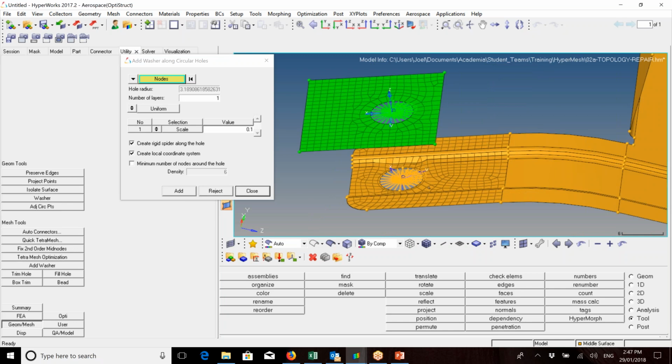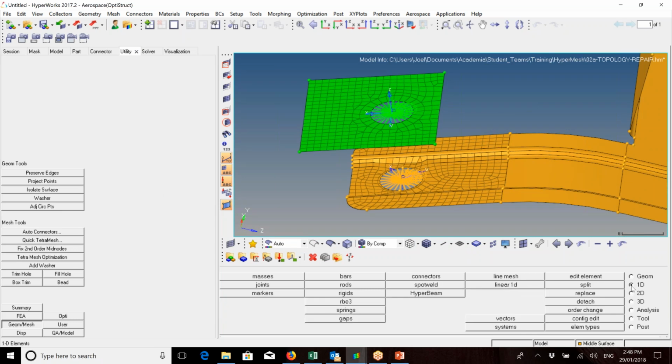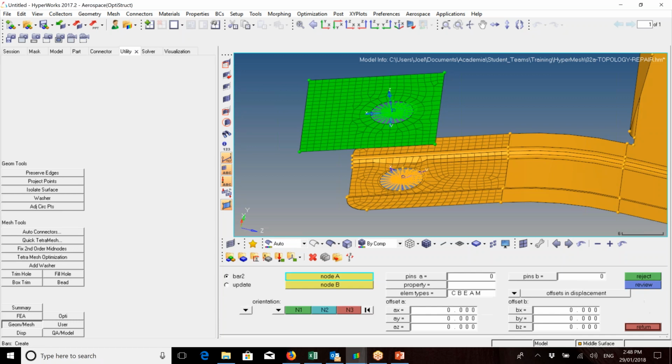Okay, so that's gone over fast, some rigid meshing, some 2D meshing. Now I'm going to show you how to quickly do your 1D meshing for bolts or axles, beams, bars. The good thing is this has already created our nodes for it as well. So on the panel here, you can hit 1D, go straight to a bar. First off, select your orientation. So N1 will be this node here, N2 will be that node. And now you don't need a third because we're only connecting 2 nodes.